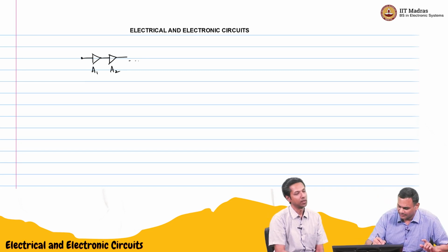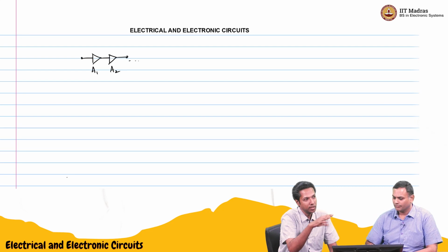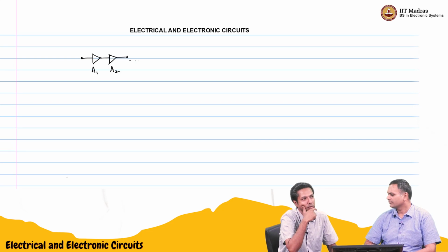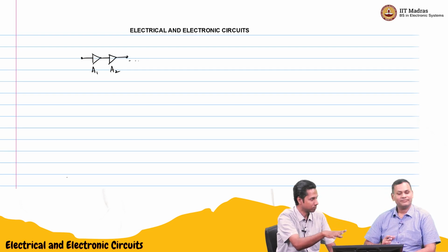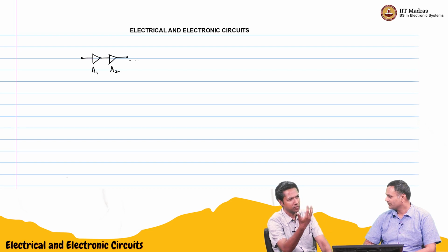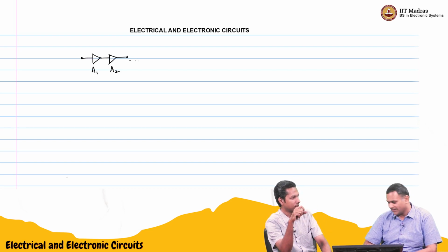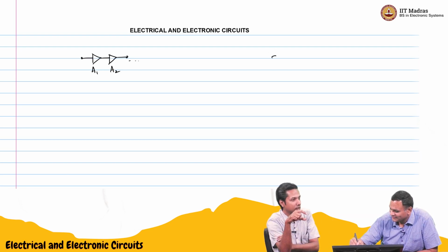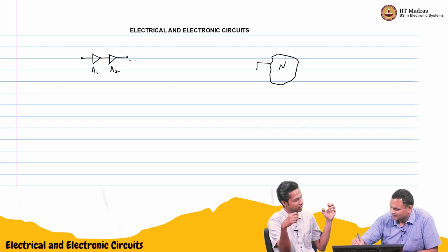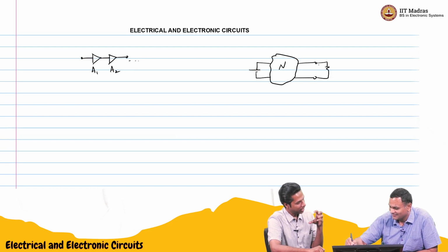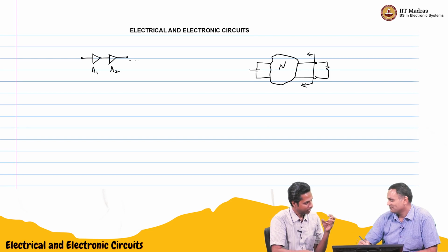Initially we learned about circuit analysis, and we used that to analyze a circuit. Later we also learned Thevenin, Norton, etc. That also we used in this. But with Thevenin, I get information from the output side. I know this is the internal impedance of the source, and this is the source I will have. But I have no idea from the input side how it will look, because if you want to cascade, I need to know how it will behave in this circuit as an input.